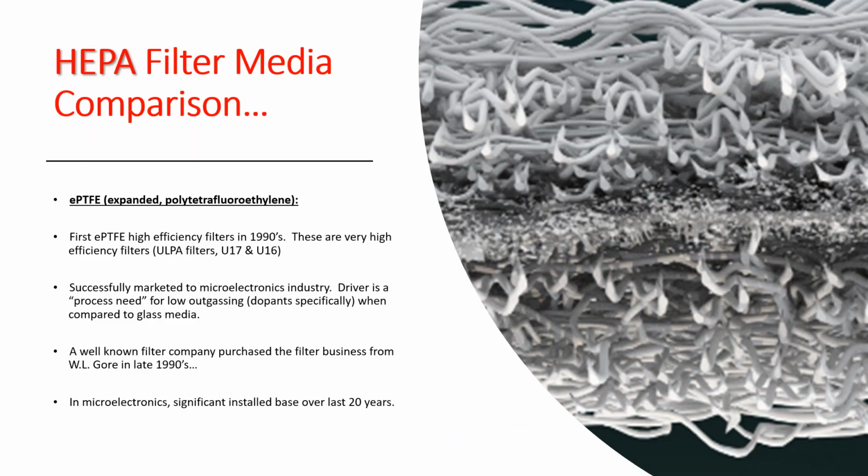One of the other medias that was introduced over 20 years ago is actually what's called expanded polytetrafluoroethylene, or ePTFE. And some people have misnamed this as Teflon, which is not technically correct. It's not Teflon. Teflon is actually just PTFE. This is expanded PTFE. Teflon is actually what you see in window wipers or in pans that's being sold on the shopping network or at Canadian Tire. It's not what's used in filtration.